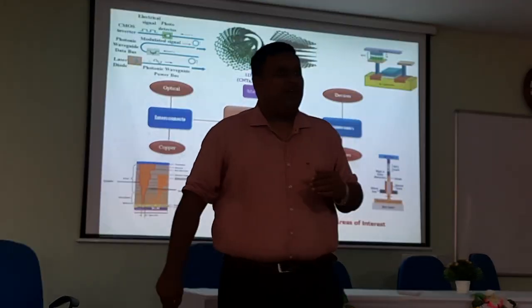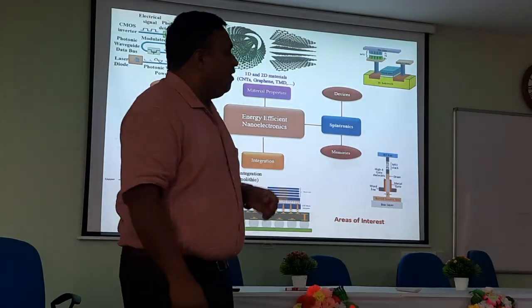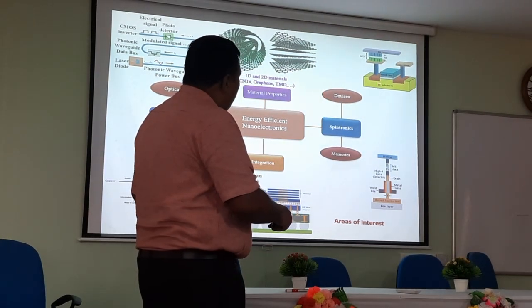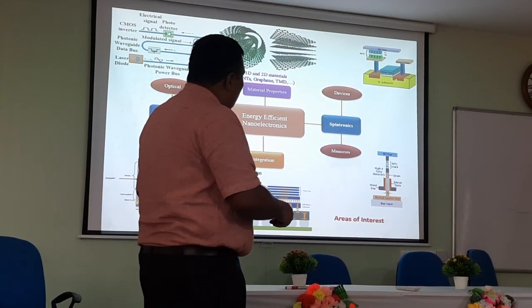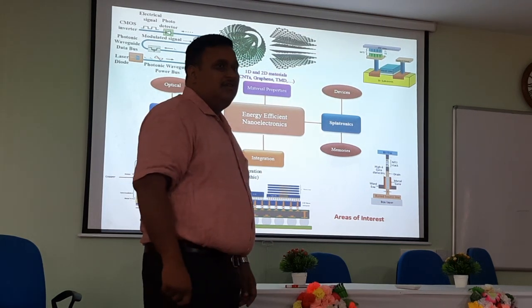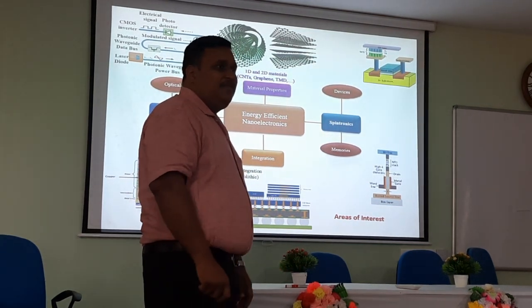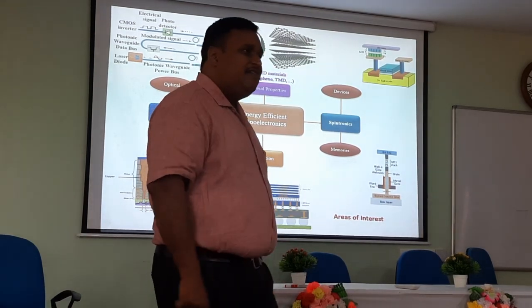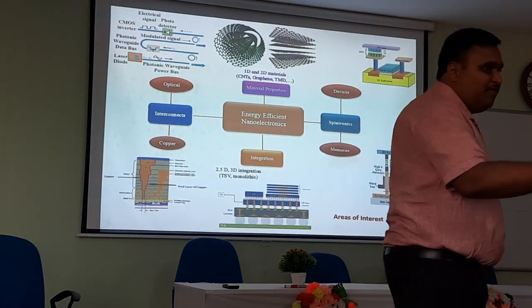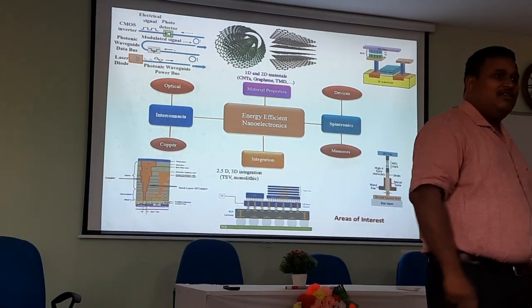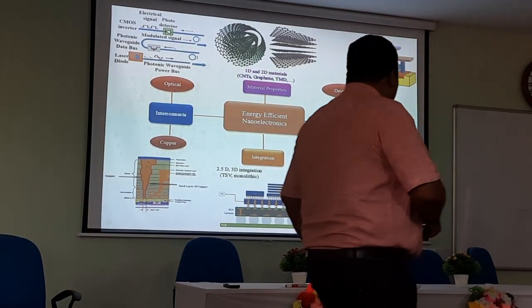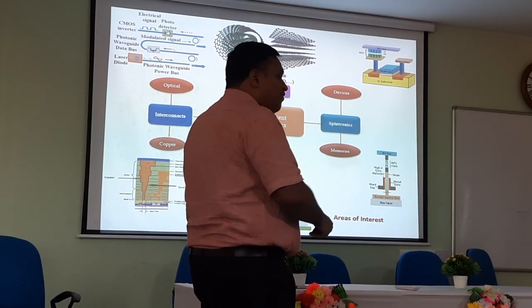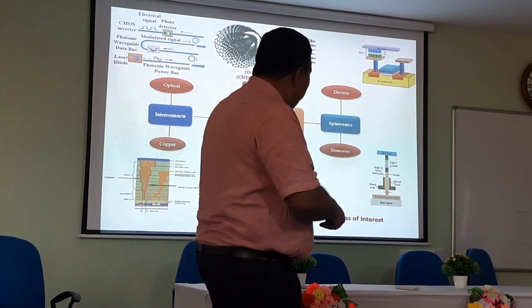So what Shivam Verma actually thought of while going through this research was that what we are seeing is still the overall area of a single cell is all because of this planar transistor. The MTJ is still very small. So why don't we use a gate all around, which is smaller than your planar transistor? I said, wonderful idea, why don't we go ahead with it? That's fine. Let us go ahead with this gate all around transistor. Still, the gate all around transistor is occupying more area in comparison to your MTJ.